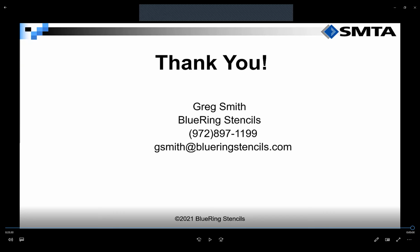So I would use either that rotated U shape or that rotated inverted home plate to remove paste from the outside edges, and then see if that helps. So you're not only removing paste from the outside of it, but you're also removing volume, right? So that 20-25% less volume can help solve that tombstone challenge there.